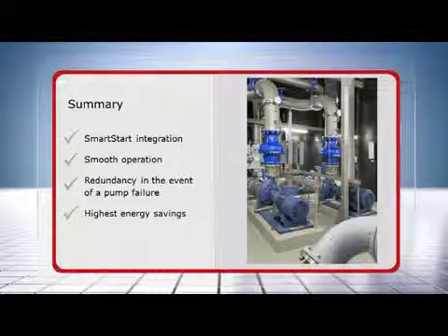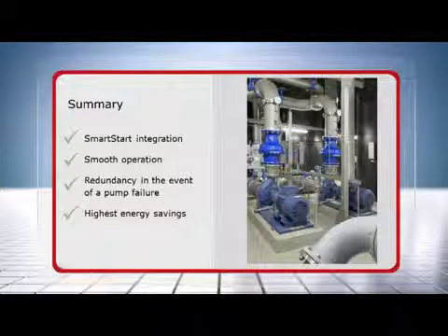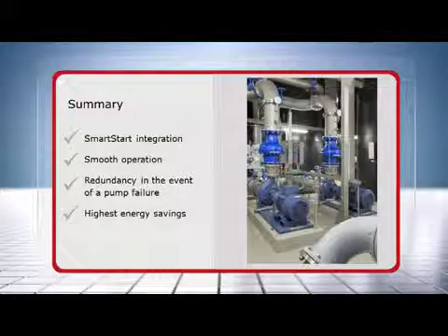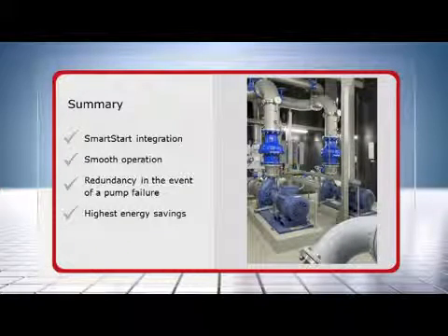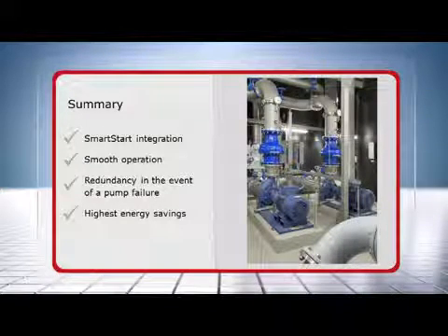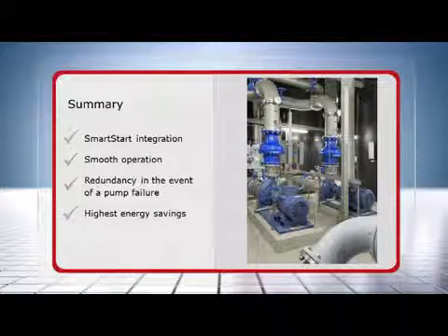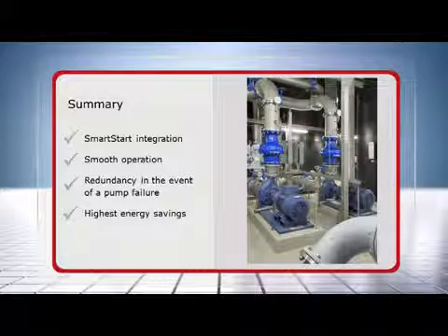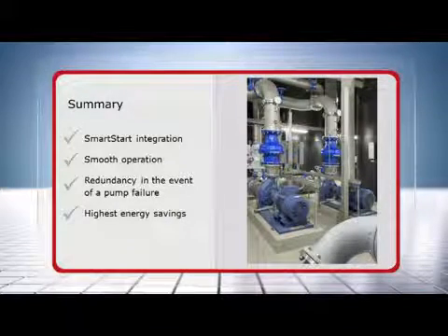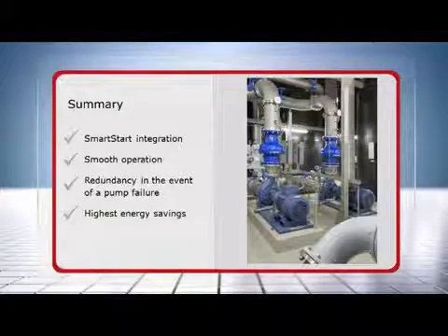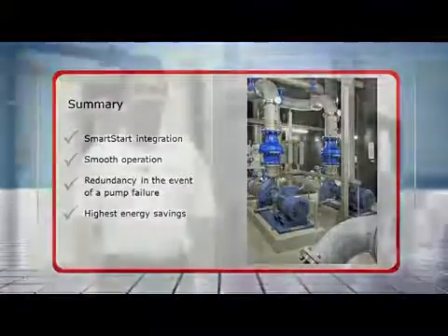In a master follower application, all pumps run at the same speed. Sharing the load between the pumps in the system ensures a highly efficient operation. Load sharing also saves energy by continuously monitoring the energy consumption and adapting the staging speeds if required.